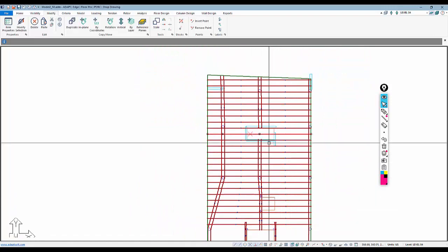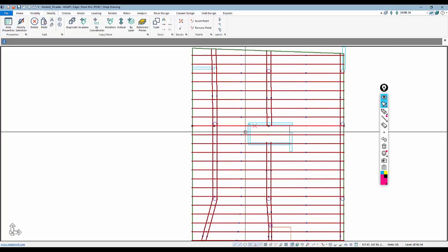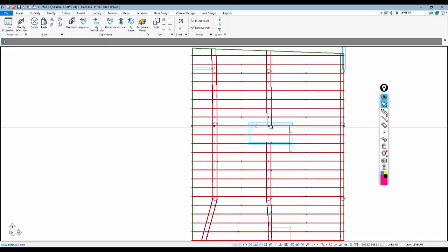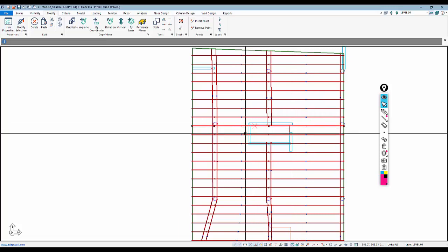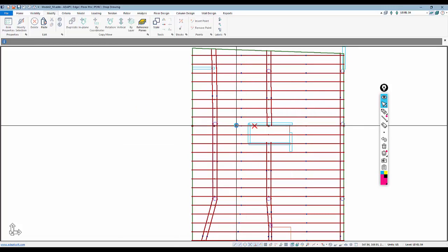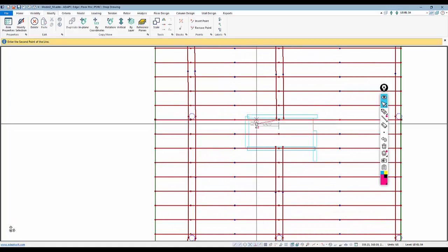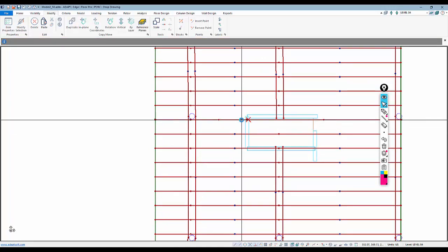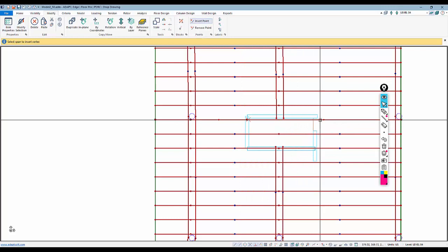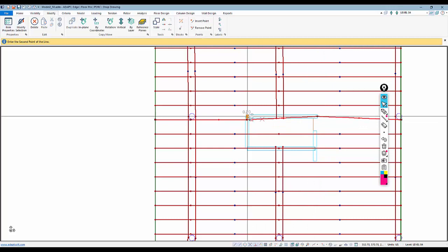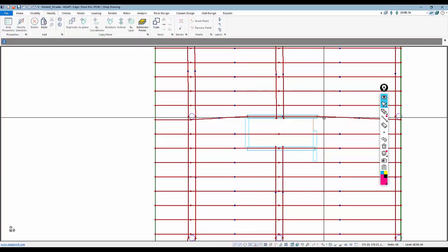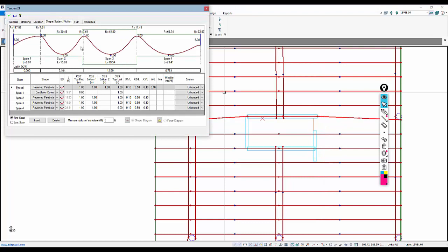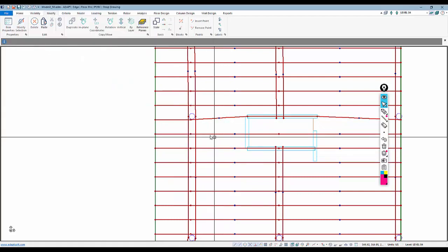And now this tendon here, I'm going to actually just take this tendon and say, okay, here we have a wall, so I'm going to adjust that actual tendon. Let me save this, and for that tendon I'm going to move this point over. But I also want to right click and insert another point. So this inserts another high point, and that other high point is there. So I'll just move this tendon here along this wall. And if I double click on that span along the wall, which is span 3, I don't need any drape there. There's a wall there, so I'll just make that straight and be done with it.